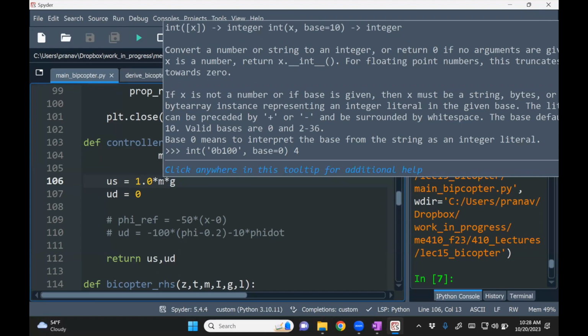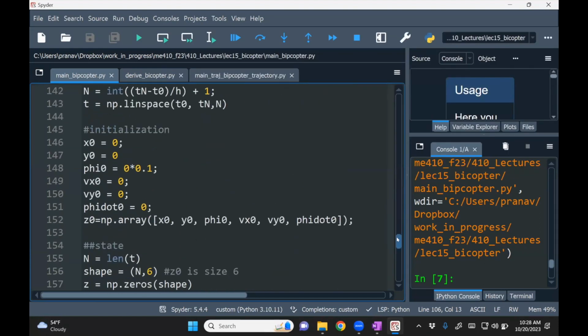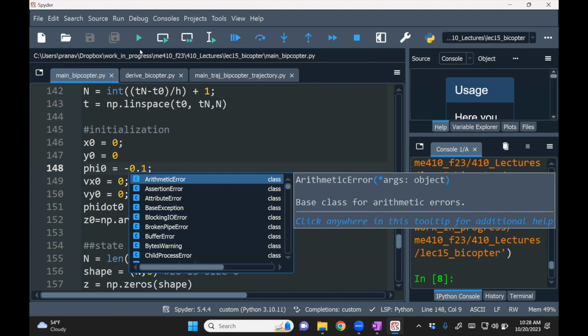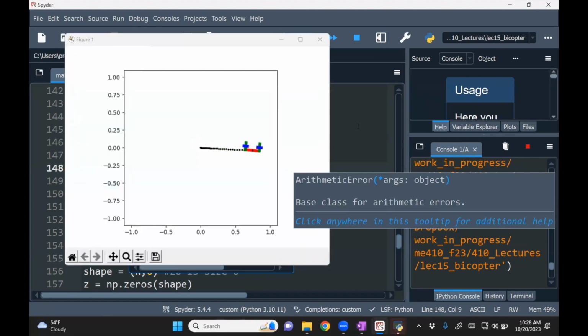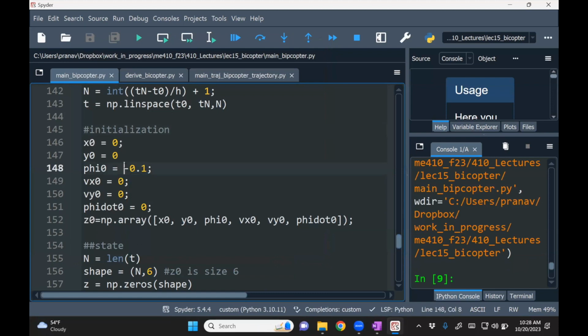So let's keep it put and change phi now. Instead of having a phi of 0, let me put 0.1. Okay, so the hunch is that if you tilt it slightly, it starts accelerating towards your left. You see it goes to the left. And then if you do it the other way, it goes to the right. Okay, so with those things, you can actually intuitively build a controller. You don't really need any fancy control theory. Just those observations, going up, going down, left and right, you can combine them in smart ways to make it go left, right, up and down.